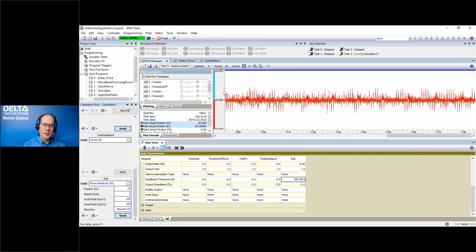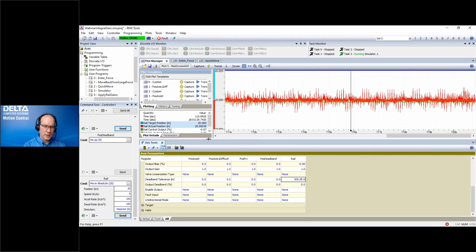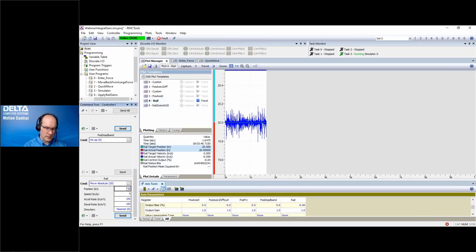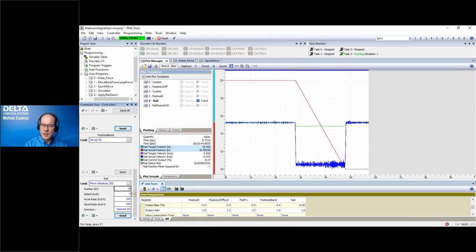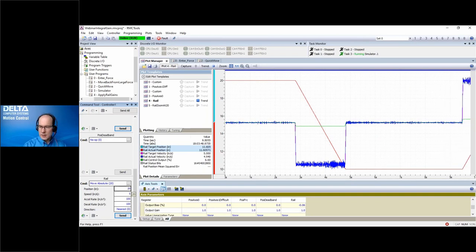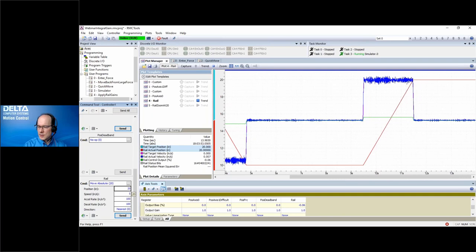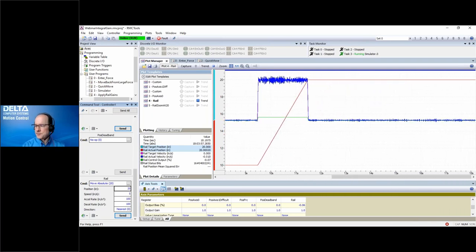And this deadband tolerance, it doesn't really affect anything else. If I do a regular move here, let's see if we do that one, we see that it's still tuned up plenty fine. It's just that when I get to position and am holding position, then it doesn't have that small oscillating. So it's a pretty cool feature to use to prevent the integrator from bouncing around.